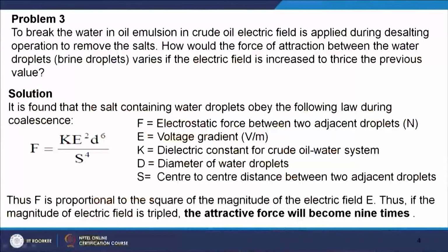Our next problem says, to break the water in oil emulsion in crude oil, an electric field is applied during the desalting operation to remove the salts. How would the force of attraction between the water droplets vary if the electric field is increased to thrice the previous value?